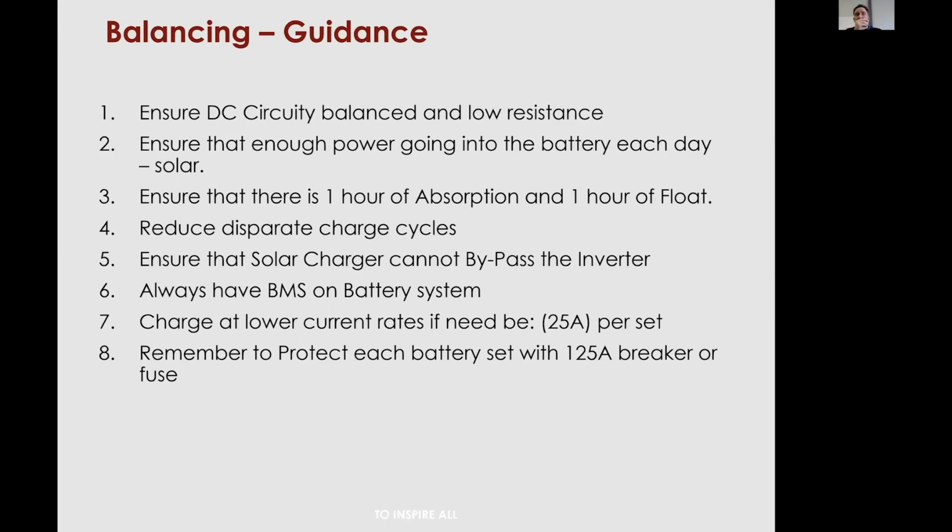And the end result is when you actually are wanting to push out during the evening, you may be at a lower absorption, and you may have lost the synchronization between the BMS state of charge and the actual state of charge. It's not a big deal, the batteries will still deliver all of their power. It just won't report as nicely to the inverters and so forth.